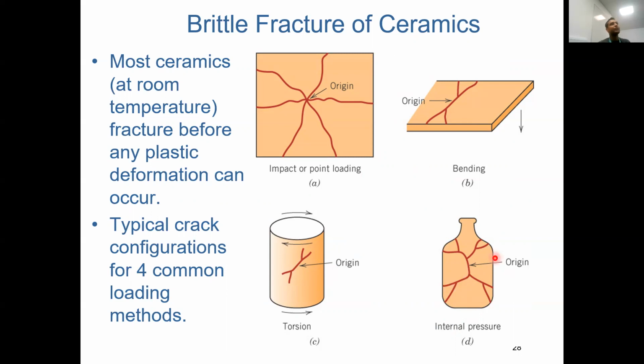This is the first thing when you arrive at the failure scene or do a failure investigation, to see how things break. The first thing we do is visual inspection. We look at how the material has failed, at the shape and size of the crack and the broken specimen. Based on that, we can find out whether the force was applied from outside, a bending force, or internal pressure, or whether it was torsion, and so on. Okay.